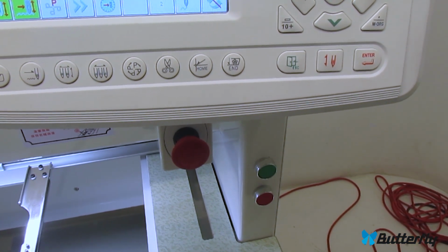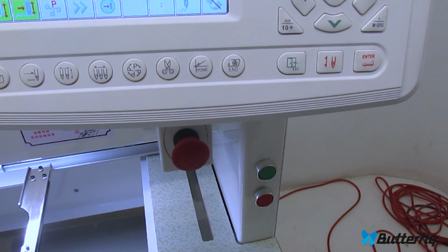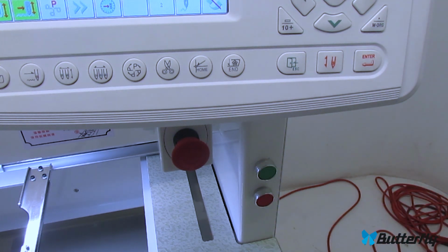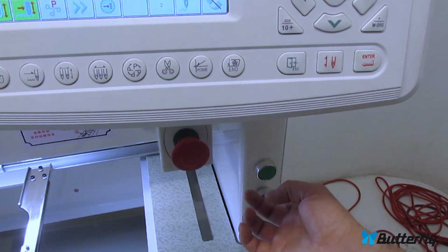If you do run into any kind of thread breaks or anything like that, or your bobbin runs out, the machine will automatically stop, and it might move a few stitches ahead. So what you can do is press the red button to back it up. If you press it once, it'll go back 1 stitch. If you hold it down, it will return many stitches. And if you hold it down long enough, it will continuously return until you press the red button again to stop.